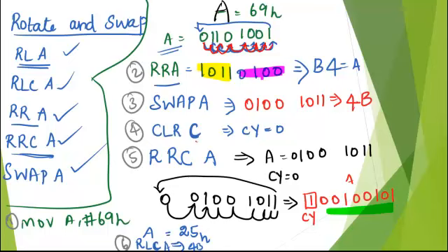And the least significant bit will go to the most significant bit. So what will be the data? Now it will be 1 over here and then shift all the other bits: 1, 0, 1, 1, 0, 1, 0, 0. What is 1, 0, 1, 1? That is B. What is 0, 1, 0, 0? That is 4. Now the accumulator will have B4 in it.